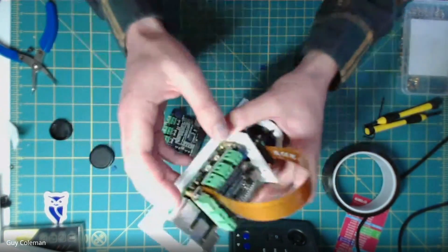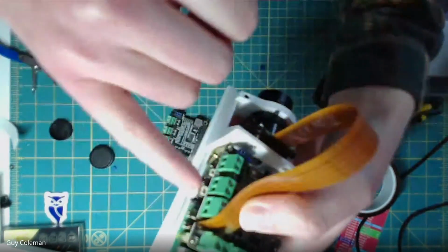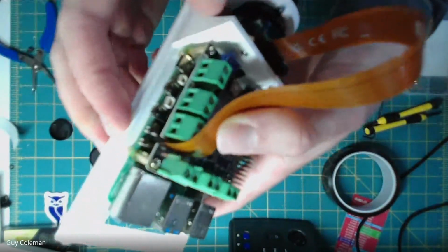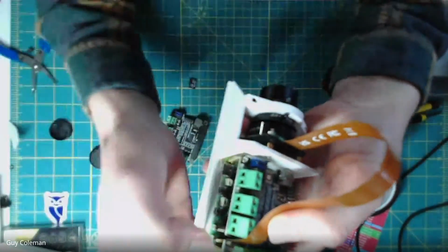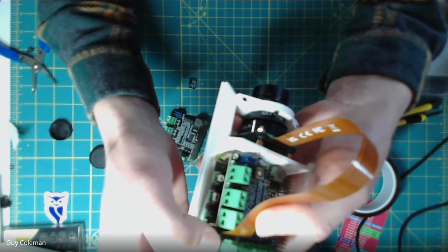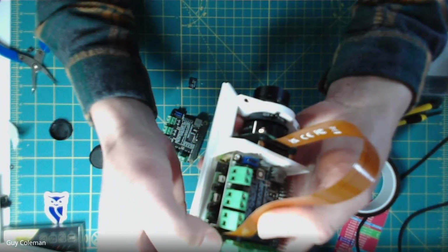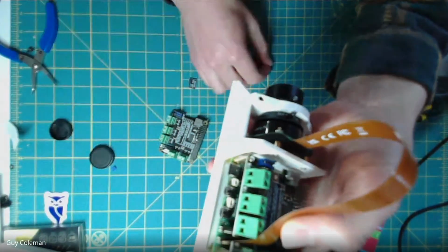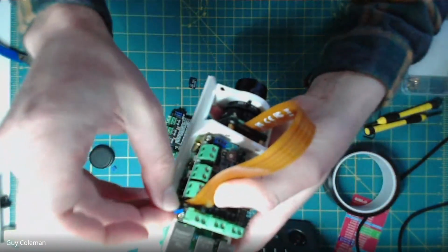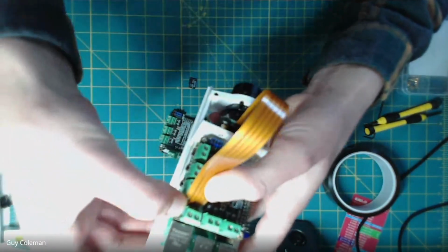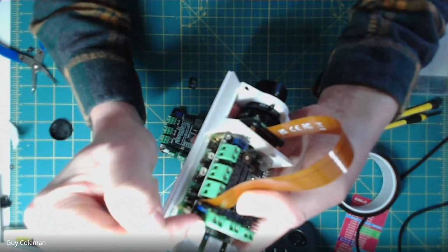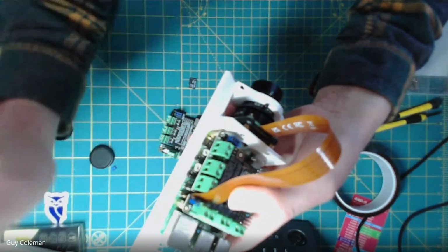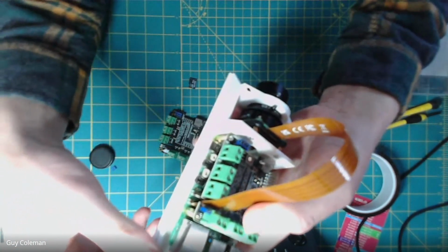Then the final set of these enable sets. This is a new one. I think you should be able to see it on the screen. Hopefully it focuses better. This enable set will enable all the outputs. By default, they'll all ship when we send them out to people with a pin over this, like so, because you only really need this input if you are to start using it, say, for section-based control, or if you want to turn all the outputs on and off with a switch that you've wired up separately.